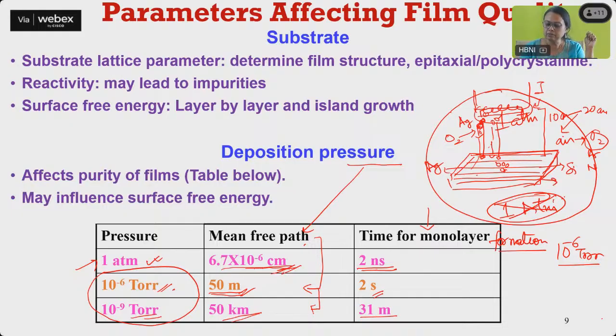But in between the evaporant and the substrate, this path is free. No disturbance is there in this path. So that is why, when we are depositing a good film, we want to have maximum mean free path for our evaporants. That's why vacuum is important.